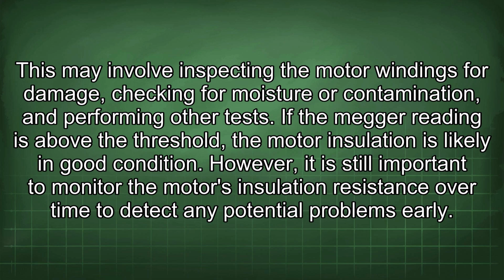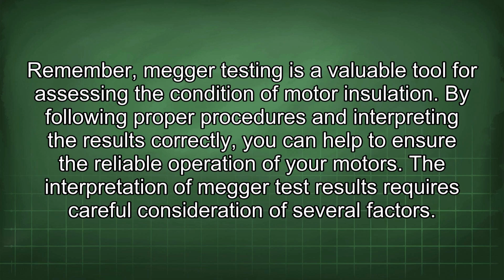If the Megger reading is above the threshold, the motor insulation is likely in good condition. However, it is still important to monitor the motor's insulation resistance over time to detect any potential problems early. Remember, Megger testing is a valuable tool for assessing the condition of motor insulation. By following proper procedures and interpreting the results correctly, you can help to ensure the reliable operation of your motors.